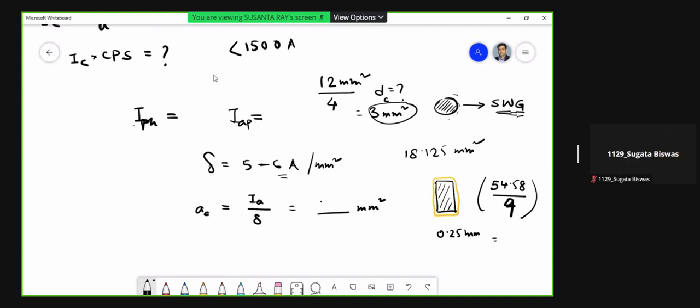That's right, the size, because the weight of the lead acid battery is quite high, because the energy density is not that high compared to other options like lithium ion battery, nickel cadmium or nickel metal hydride. All those batteries have quite high energy densities compared to the lead acid battery. Lead acid battery has certain advantages, but as far as mobility is concerned, you have to reduce the size as well as weight, isn't it? Yes, sir. So that is the constraint.